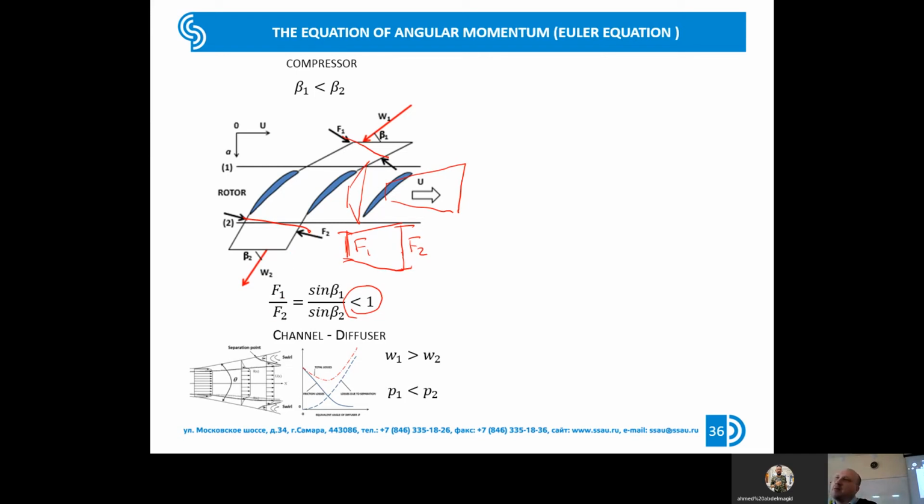That's why finally you have some optimum diffuser factor, because you need to find a good combination between the separation losses and the friction losses. So typically this opening angle of the diffuser, I think, is 16 degrees. It's a typical value which allows you to slow the flow without strong losses, without separation.